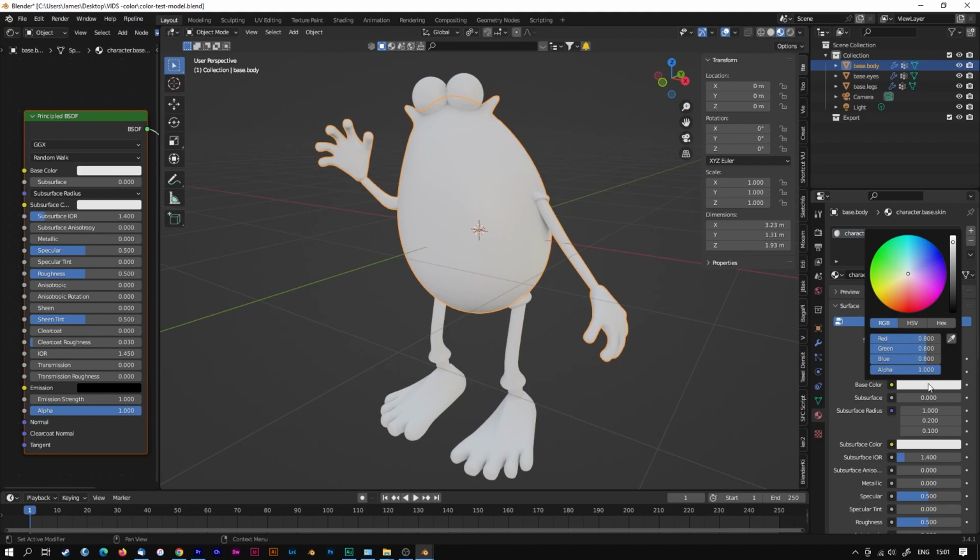There are a number of ways to generate colors using the color wheel. You can select a color by single left-clicking or left-clicking and dragging within the color wheel itself to choose the color's hue. The light and dark for the color can be controlled by single left-clicking or left-clicking and dragging on the value bar to the side of the color wheel. You might want to spend a little time practicing mixing various colors before moving on.